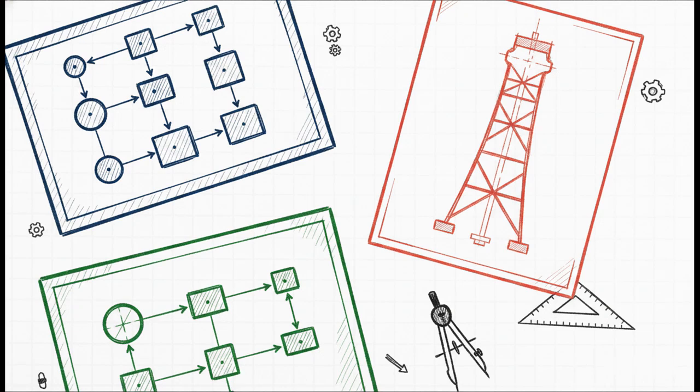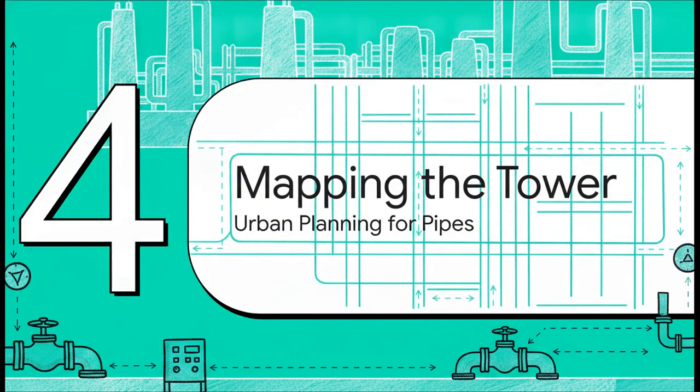The P&ID gives you the process data, the plot plan dictates the tower's physical relationship to other equipment and main pipe racks, and the fabrication drawings give you the exact diameter, height, and locations of those internal trays we just talked about. You simply cannot design a vertical city without fully understanding the required equipment elevations, pipe sizes, and operating conditions first. Which brings us nicely to Section 4, mapping the tower.